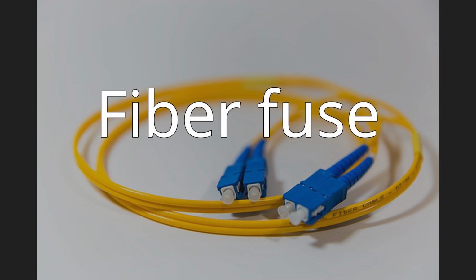The open fiber control system, which ensures laser eye safety in the event of a broken fiber, can also effectively halt propagation of the fiber fuse. In situations such as undersea cables, where high power levels might be used without the need for open fiber control, a fiber fuse protection device at the transmitter can break the circuit to keep damage to a minimum.